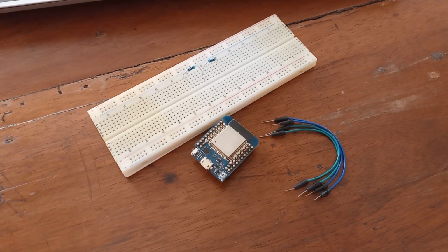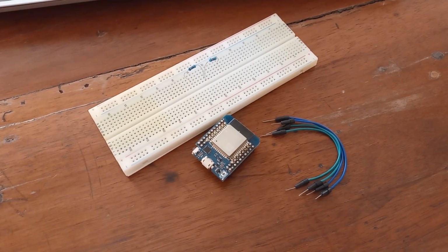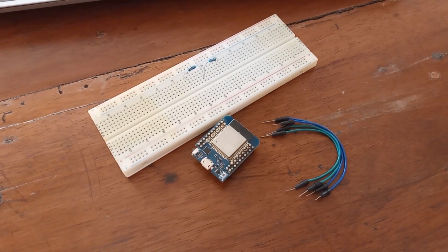Well, timer is the simplest of all. You just need to set time when you want your microcontroller to wake up. Touch signal, it's also self-explanatory. Whenever you deal with that particular pin that is considered to be touch pin, your microcontroller is going to wake up. And finally, I'm going to show you how to wake up your microcontroller with external signals. Well, touch signal is also external signal, but in this case, we are just going to set some pins to high or to low in order to wake up our microcontroller. And we actually have 2 functions for that.